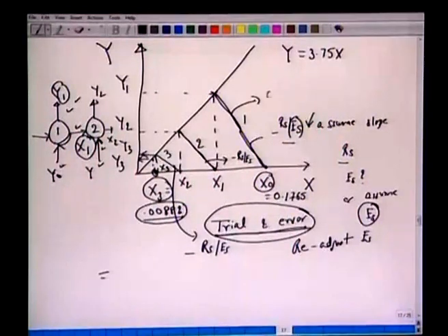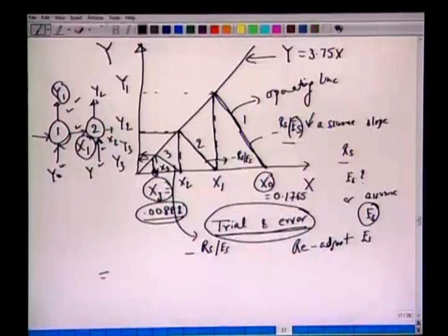All right. Also important to note that these points we have been able to mark. This is the operating line, and this is the equilibrium line. We realize that the two exit streams are in equilibrium. So y1 x1, y2 x2 and y3 x3 are on the equilibrium curve; the coordinates are on this equilibrium curve.